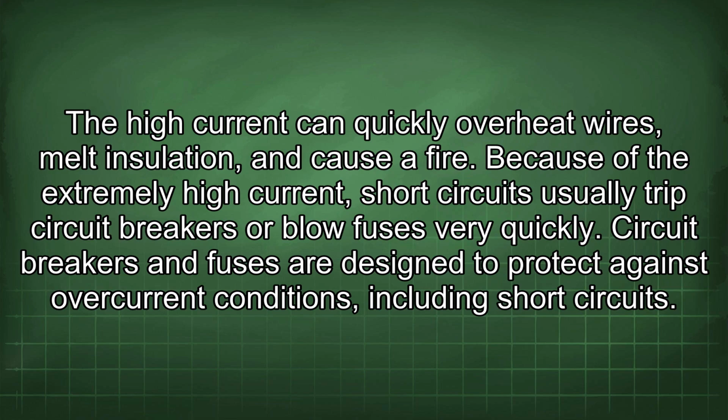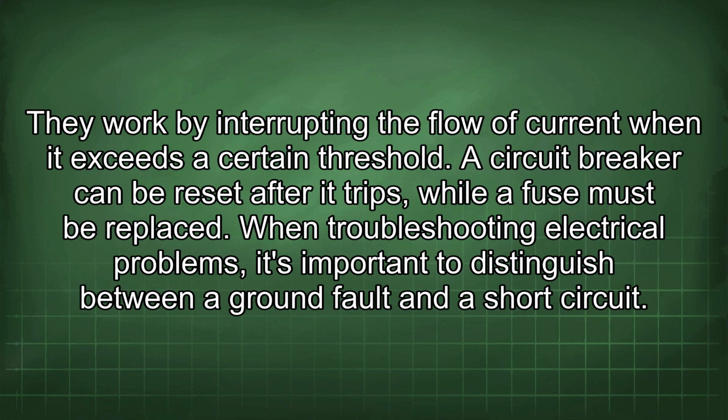Circuit breakers and fuses are designed to protect against overcurrent conditions, including short circuits. They work by interrupting the flow of current when it exceeds a certain threshold. A circuit breaker can be reset after it trips, while a fuse must be replaced.